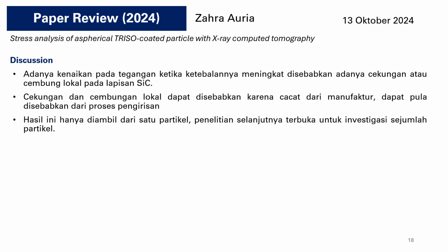To wrap things up, there is an increase in stress whenever the layer thickness is increasing, and that is caused by local concave or convex areas on the silicon carbide layer. And these local convex or concave areas are caused by manufacturing defects or the slicing process. And we have to take note that this result is only for one particle, so we can investigate a number of particles for further research.